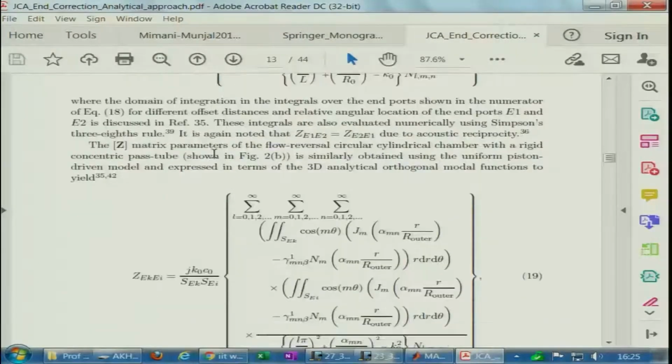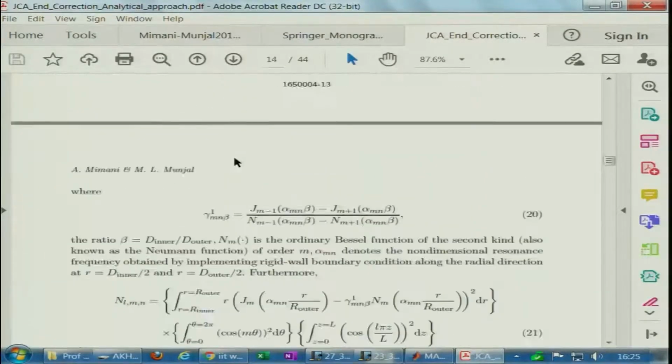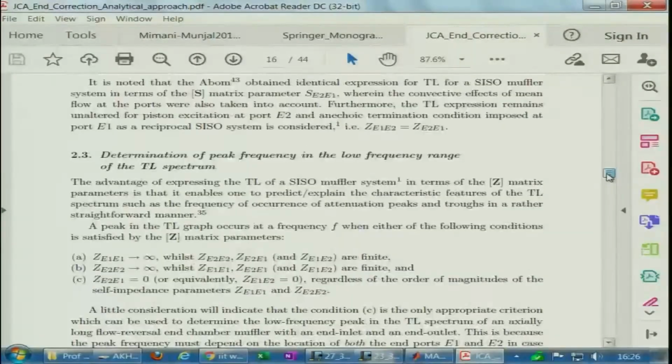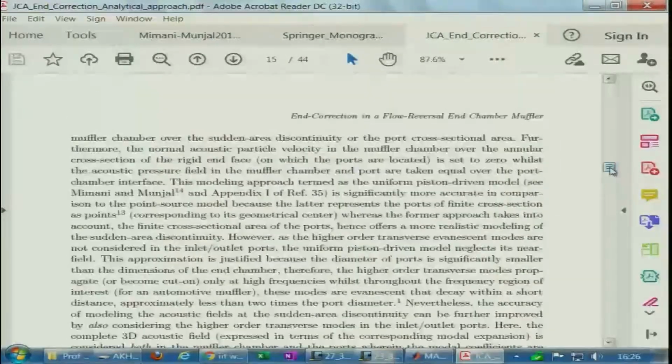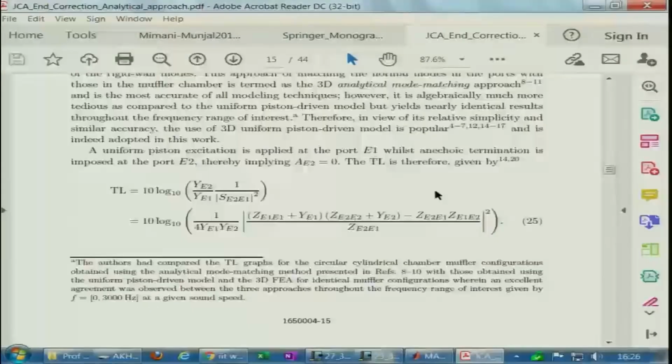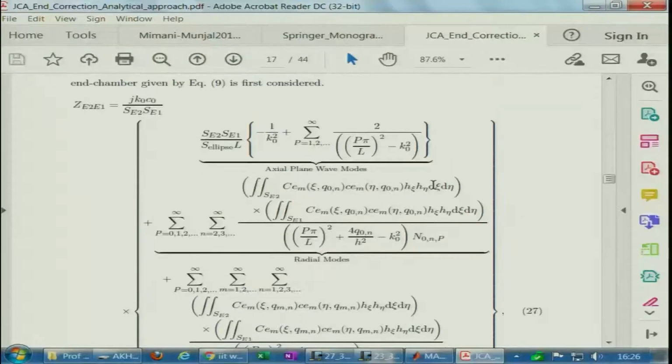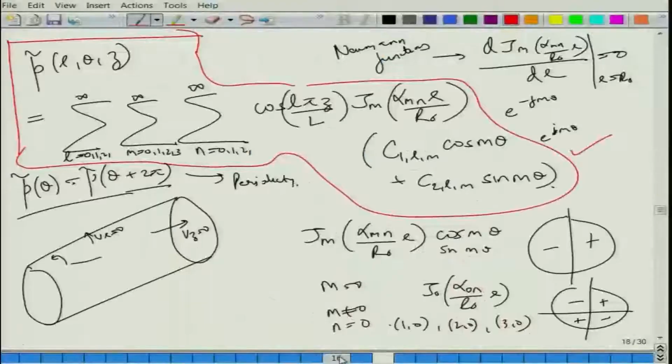The other thing that I just wanted to talk about, very briefly, is that solving for the impedance matrix parameters by solving this inhomogeneous system of equations subject to homogeneous boundary conditions is the same as solving a homogeneous Helmholtz equation subject to inhomogeneous boundary conditions. So, what do I mean? This would require a little bit of elaboration, more of a conceptual thing.